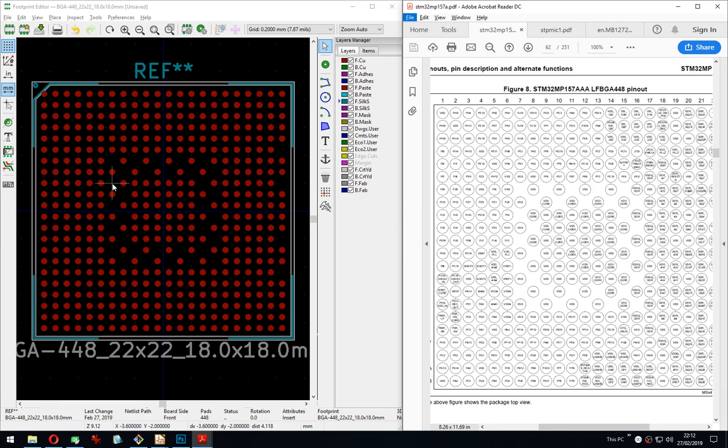So on the SAM there is the bootstrap program, and on IMX chips, I think they actually use a stripped down version of U-boot. So U-boot boots U-boot. But U-boot, kernel, rootfs, and DTS, and yeah, that's pretty much it. I mean, the DTS gets compiled into a DTB, but that's just details.